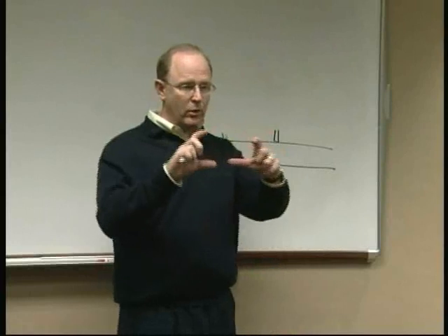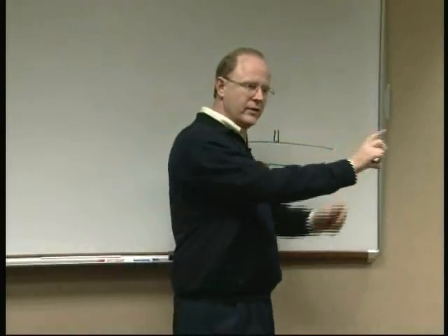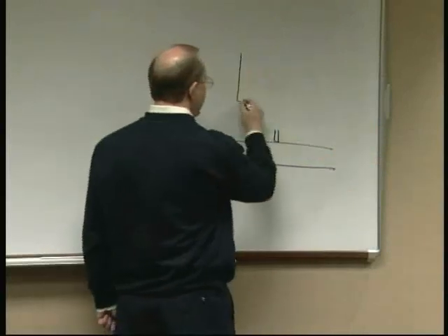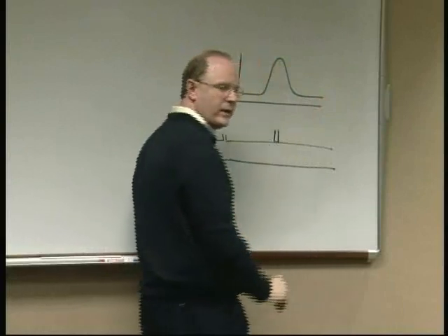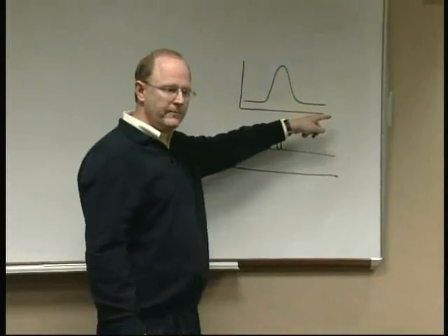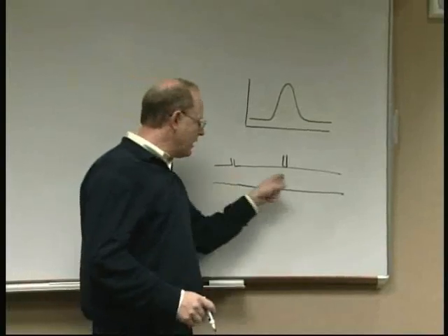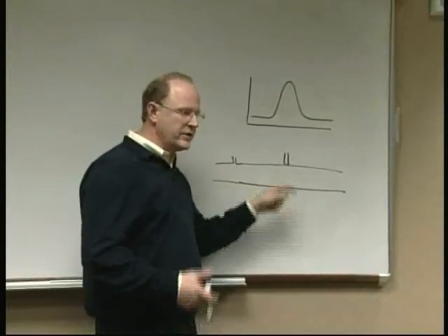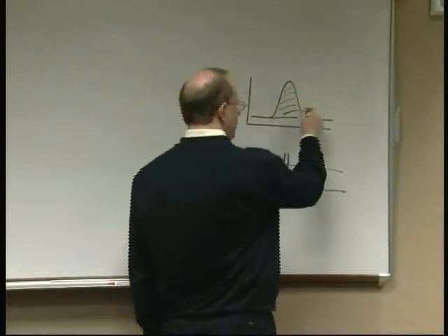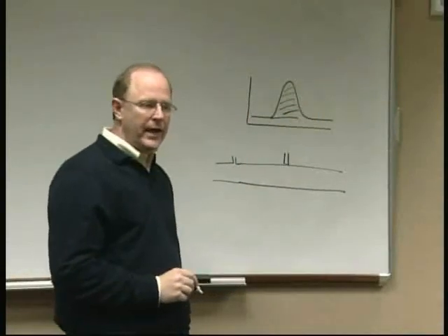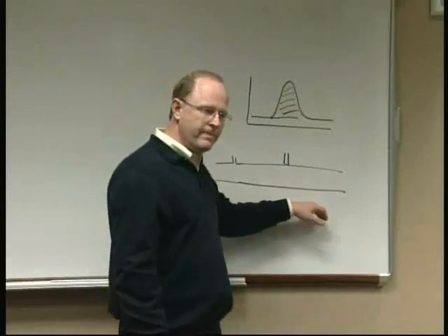When you do that, you kind of get this bolus. And so you get a little bit of dark stuff, then you get this big dark stuff, then it kind of dilutes out eventually. And if you plotted that out, you'd get this curve and then go back to normal water again, right? And it turns out if you know how far upstream it was from the measuring device, and you know how much you injected, you can take the area under the curve, and that's your cardiac output, or that's your flow through the pipe.